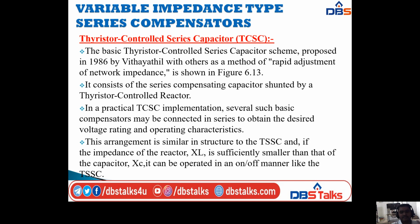So this arrangement is similar in structure to the TSSC. There is a previous method, the same arrangement, but if the impedance of the reactor, that is XL, is sufficiently smaller than that of the capacitor, that is XC, so XL is less than XC, then it can be operated in an on or off manner like the TSSC.